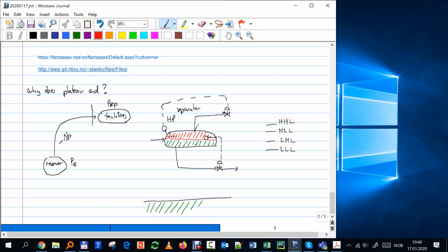Okay, if you have the gas, you have some droplets that are starting to fall down until they reach the interface and they are part of the oil. If you circulate them too fast, that means, let's say the pressure went down, volume rate went up, and the velocity is increasing, right? If the velocity of this droplet of the gas is higher, then it might not have time to reach the interface,